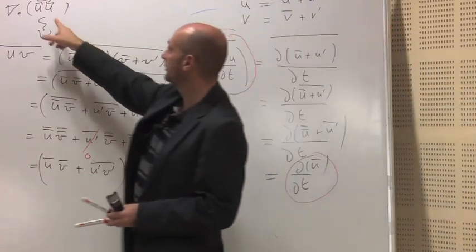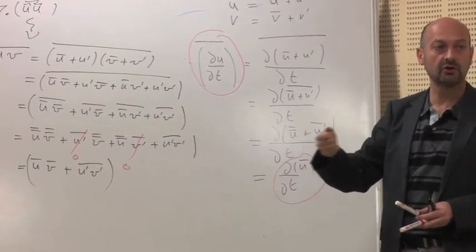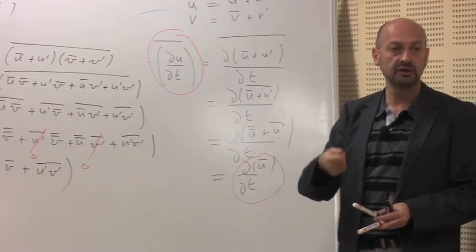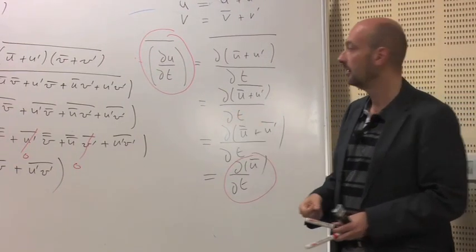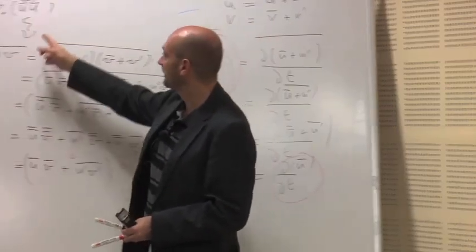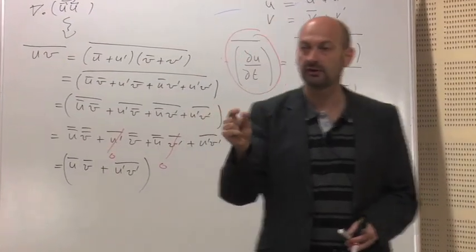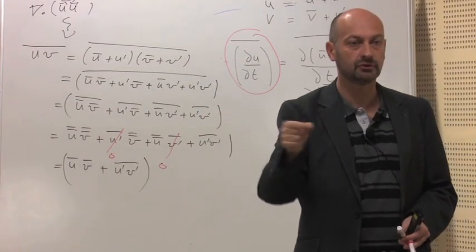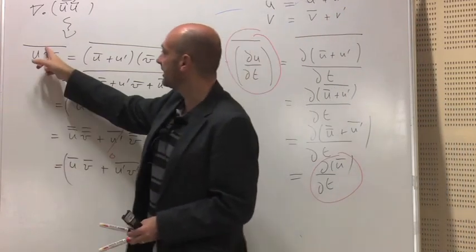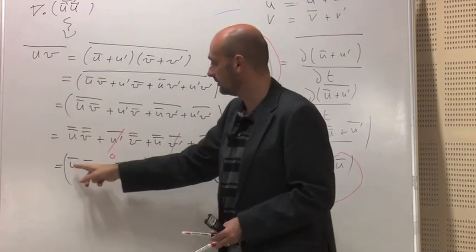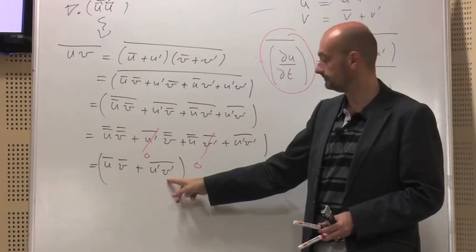But that will be the same actually for all the linear terms. Because when you take the average of a linear term, that will be the same term but with a bar. Okay? But unfortunately, in the Navier-Stokes equation, you have a non-linear term. You have the product of u by its gradient, you have the product of u by u. Okay? And when you have the product, you see that the average of the product is the product of the two averages plus an extra term. Okay? This term